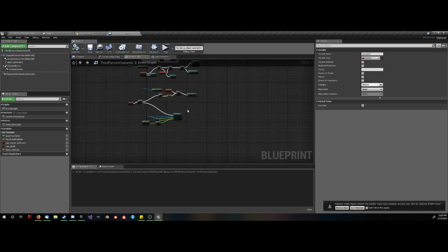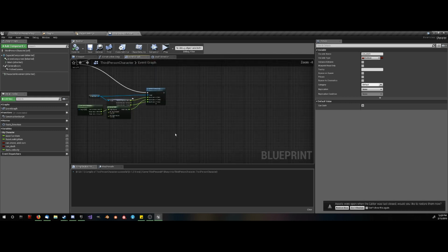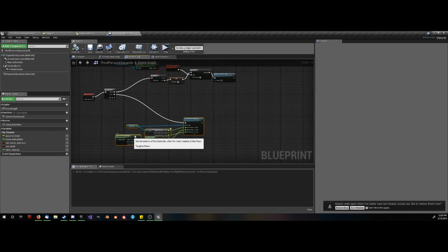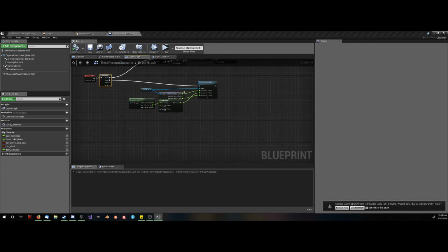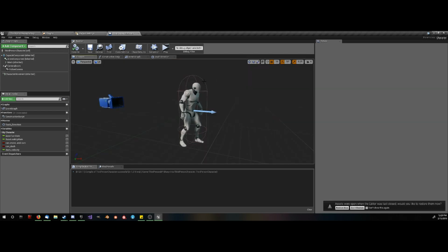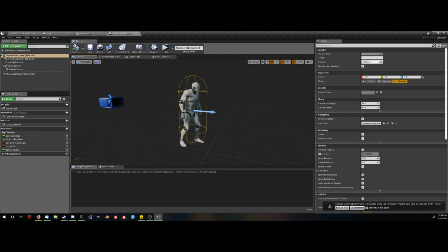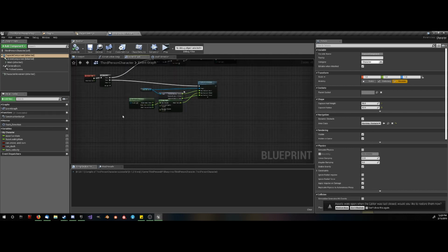Now we can build the wall jumping and the, what is it called? Wall running. Now some people have used another collision component, another sphere collision component to detect when they're against the wall, but this is not ideal because you don't get the wall's normal when doing this.